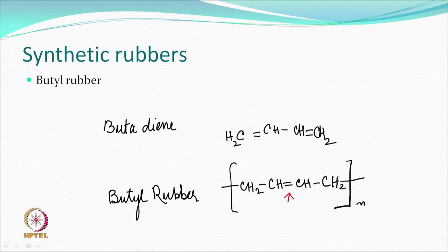Now, the hardness of this material can be changed by cross linking. This double bond will help you, right. So, those can be done like in natural rubber we talked about. Sulfur can be used for vulcanization, some of these things can be used here also. This double bond will then cross link and it will become more rigid, right.